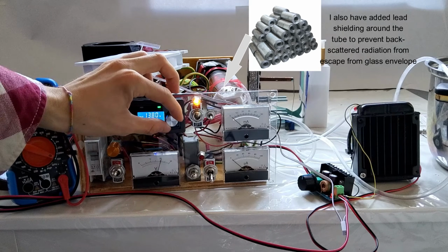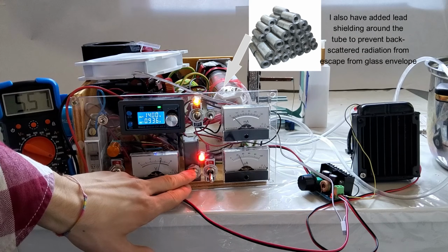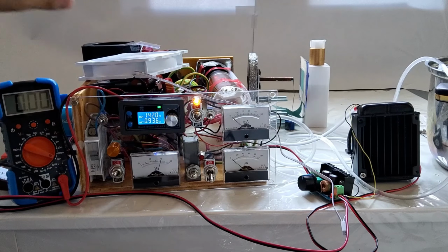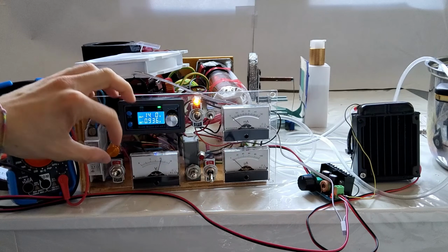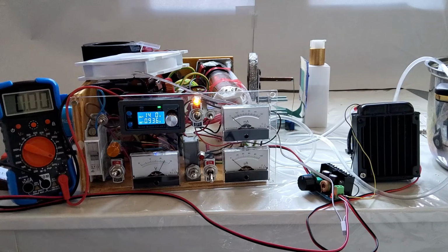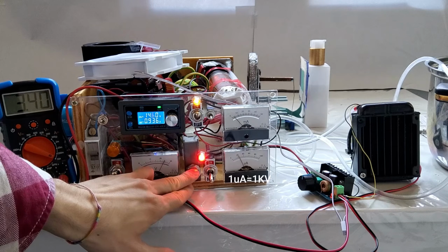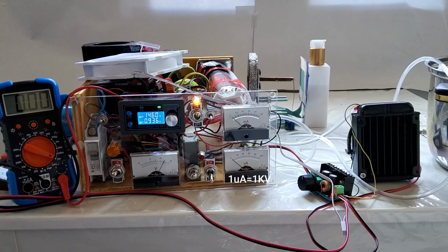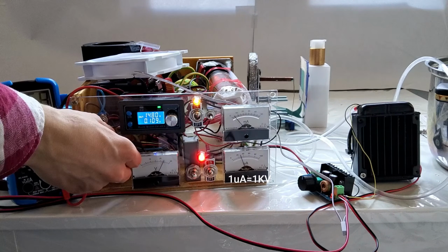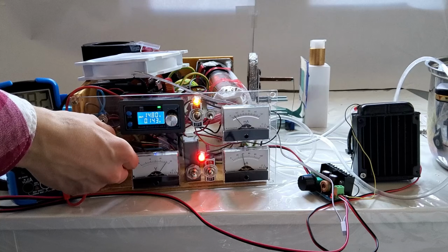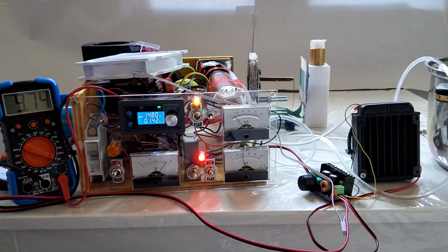Here I'm regulating the power and voltage fed to the filament and making a small test lighting on the X-rays to verify the voltage of the tube that you can see on the bottom right corner as the kilovolt meter reads. It indicates microamp, but in reality that is exactly equivalent to kilovolts. After some tests I increased the power to the maximum level, and then with the right switch on the bottom right corner I turned on the machine constantly and left the room for the exposure.